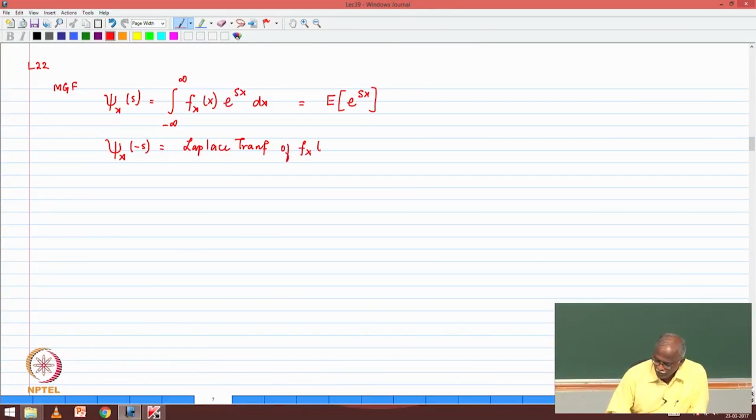Okay, so regardless of which interpretation we take, the usefulness is when we try to develop it, and one of the things that is very useful for us is the DBPSK family. It now becomes very easy for us to evaluate, because the probability of error of DBPSK in fading becomes just evaluation of the moment generating function. So let me just write the expression. It's the integral from 0 to infinity of half e power minus gamma f_gamma(gamma) d gamma.